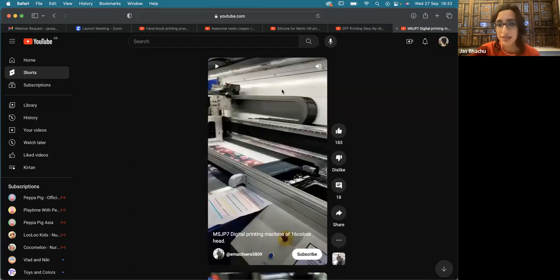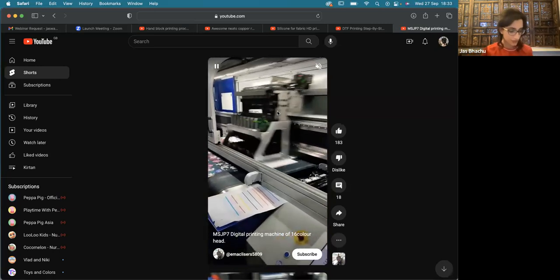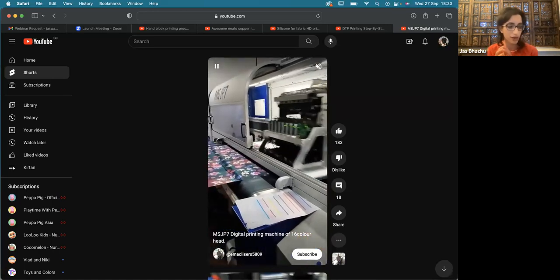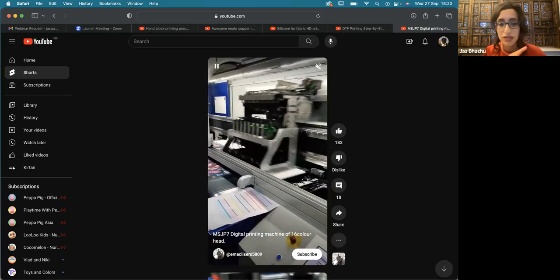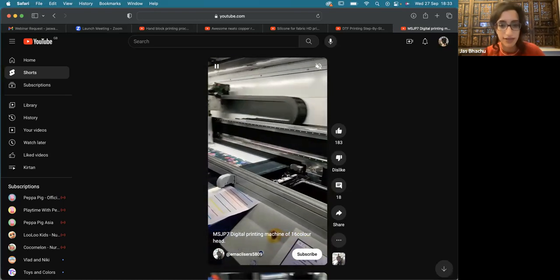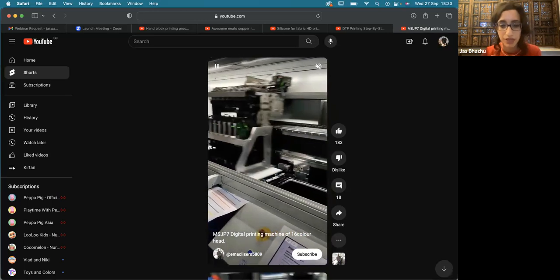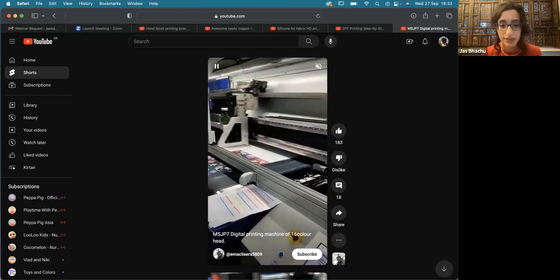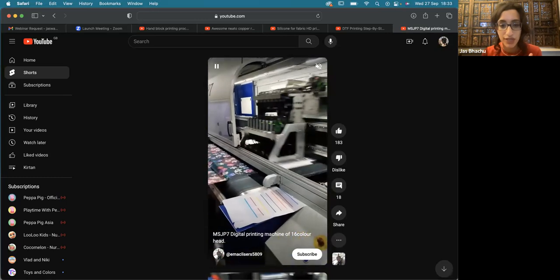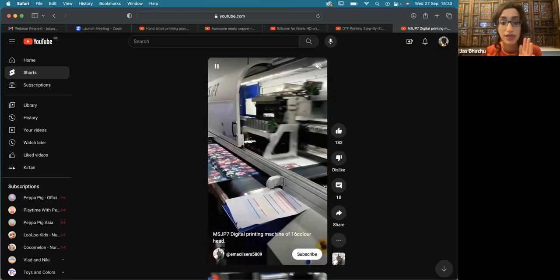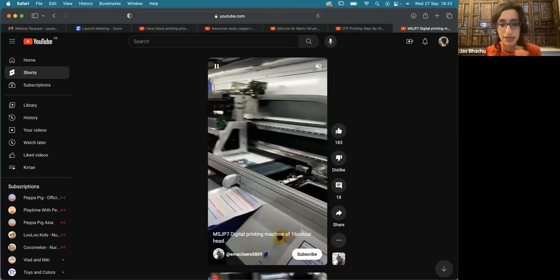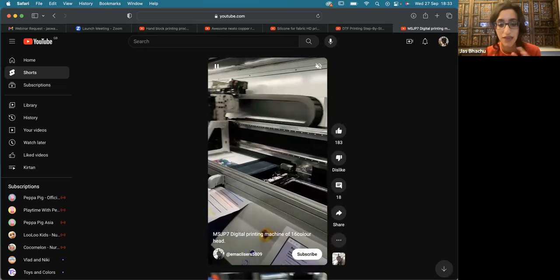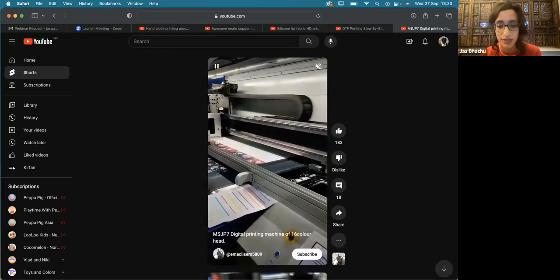And finally, in this bit, digital printing. Now, something to think about with digital print. So it's an inkjet-based method where we sort of print colorants onto a fabric. This is just like printing on paper in that sense. The fabric that you start with will always be white, and you will only get a transfer of color onto one side. Now, there is dual side digital printing that's developed, and it does exist, but it's a little bit harder to outsource that, and they generally take larger order quantities.